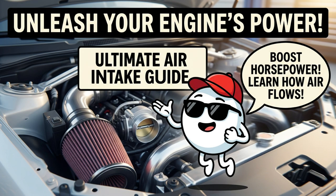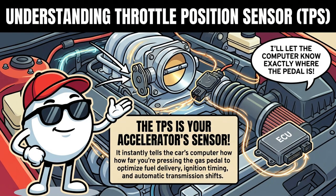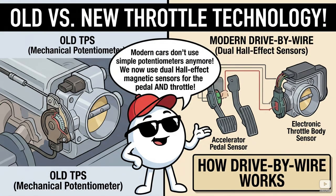the throttle plate. To adjust fuel delivery, ignition advance, and automatic transmission shift points, the computer must instantly know how far you are pressing the accelerator pedal. This is managed by the throttle position sensor, or TPS. In older vehicles, the TPS was a simple mechanical potentiometer. In modern drive-by-wire vehicles, dual Hall-effect magnetic position sensors track both the gas pedal assembly under your foot and the electronically driven throttle plate inside the engine bay.